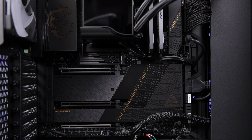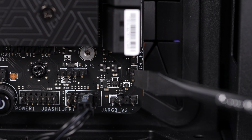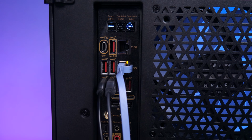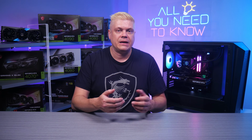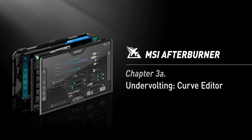Switch off your power supply or remove the power cable and use something conductive like a screwdriver or tweezers to connect the CMOS jumper pins for over 10 seconds. High-end boards may have a rear motherboard I/O clear CMOS button to do this. Then plug in or turn on your power supply and turn on your PC again.